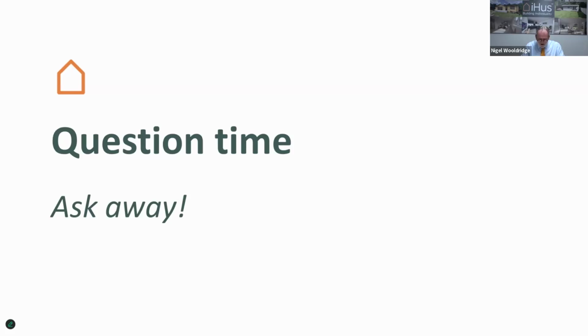And the final question from Leslie, which is aimed towards Oliver. How exact is the 50% of garden space ruling adhered to, and can IHUS be modified to adjust this? So the 50% rule is irrelevant because that's only for permitted development rights. PD rights is legislation again, which allows you to construct outbuildings without permission. It's like pre-approved permission, and one of those conditions is no more than 50% of your garden. But because we're getting planning permission, you can go to whatever size you like.